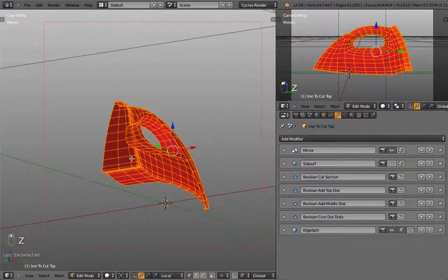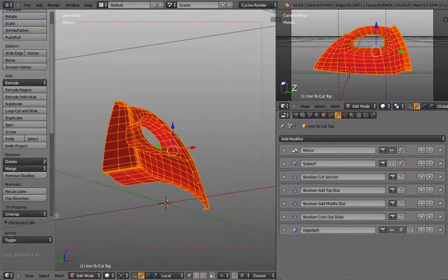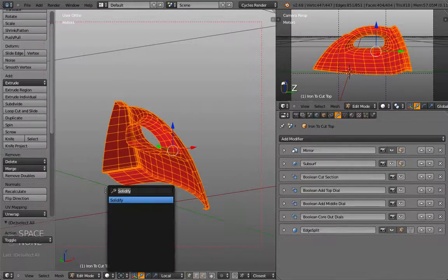Then I press T, so I have my property panels, spacebar, and then type in Solidify. You see, you have the modifier Solidify, which is interactive, and you can also offset a surface or solidify inside mesh editing through a mesh command.